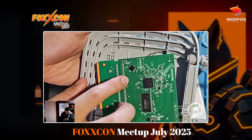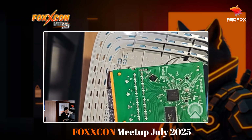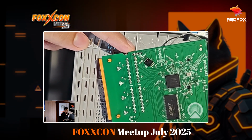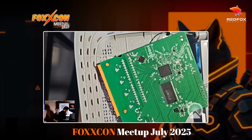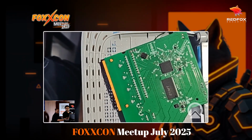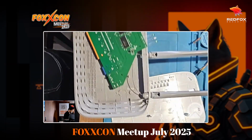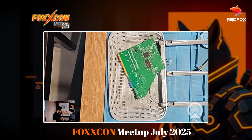All right. So as you can see, there are a lot of things going on here, but the only open ports you see are these 4 pins that are not soldered. So 4, that is generally UART, because as I said, power, ground, transmit, receive, 4 pins. So what I'll be doing right now is soldering some wires to it quickly.